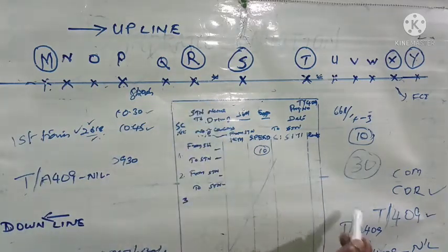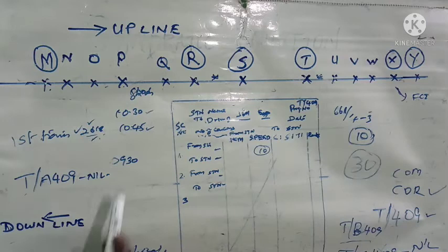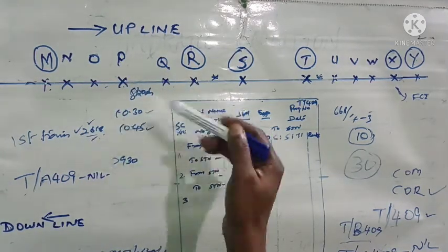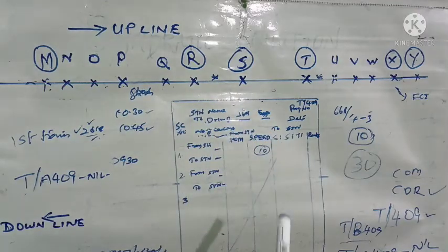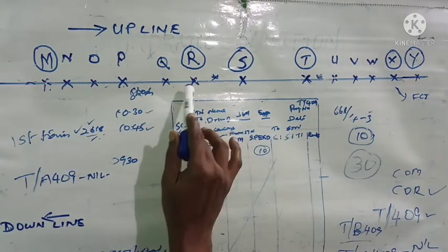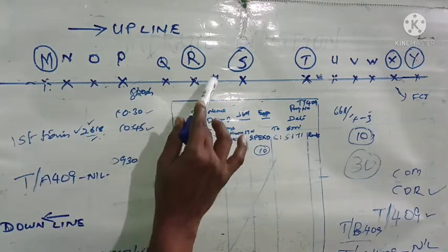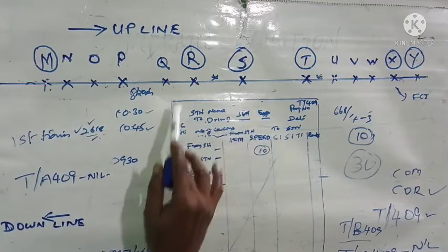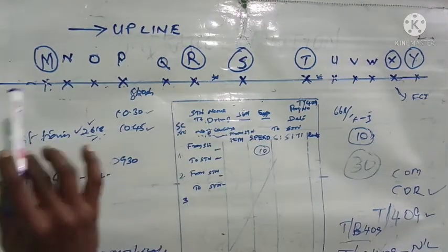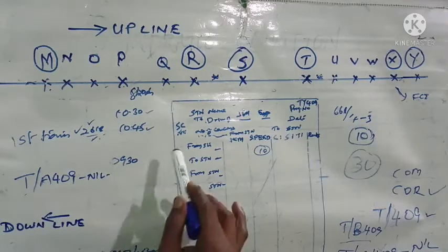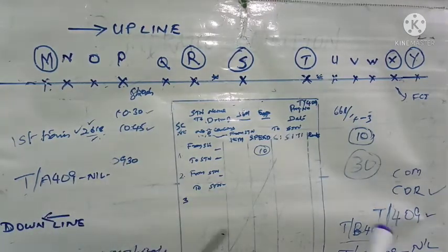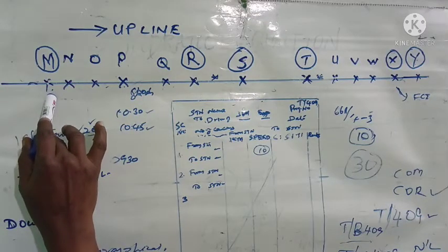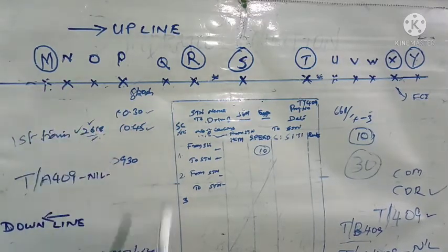The caution order number so and so. That is the caution order issued in the morning, maybe morning or 2 days back, whatever it be. The particular caution which he is going to cancel now, that will be referred. So the caution so and so at a kilometer so and so between R station and S station is lifted at 16 hours, whatever it be, at 16 hours by section engineer PY. So that message he will give to station master M, and the station master M will acknowledge it.